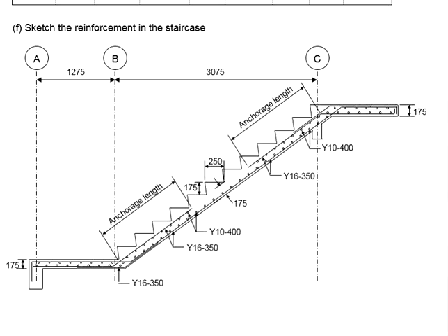To ensure the stability of the cantilever slab here, which is the landing of the staircase, you need to provide sufficient top reinforcement. The bottom reinforcement may not be as important, but the top reinforcement will be very important for the cantilever members. Such a design varies slightly when the beam is located here.